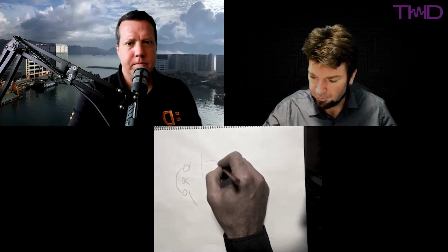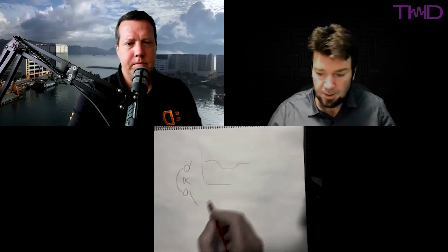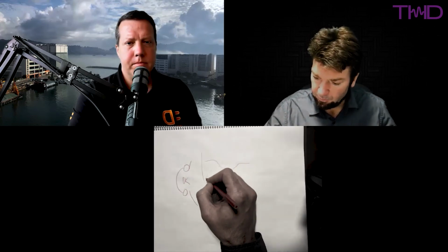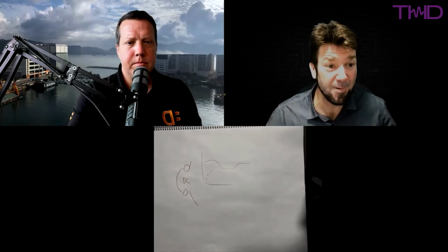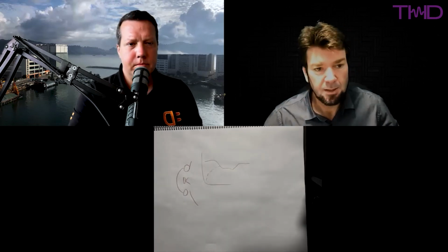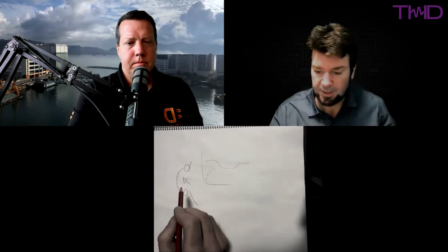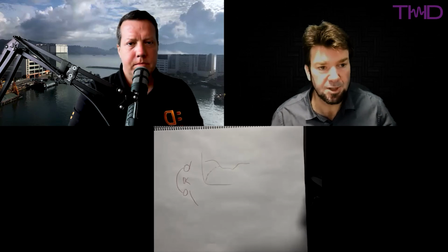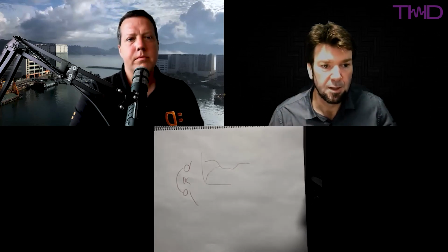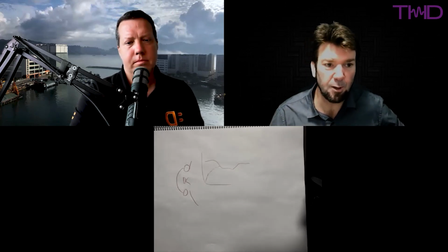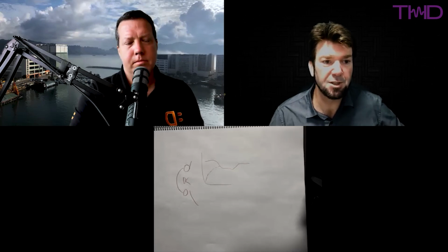So if you had designed your filter for a situation where it's perfectly sealed, and the speaker has a certain response, and you draw some kind of diagram, and then you break the seal, and all that low frequency is spilling out the gap and not getting to your ear, the filter that you computed is now totally wrong, because that speaker response has changed by quite a lot. So an adaptive filter is you're trying to compensate for those changes by changing the filter.